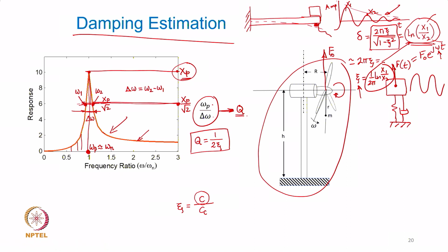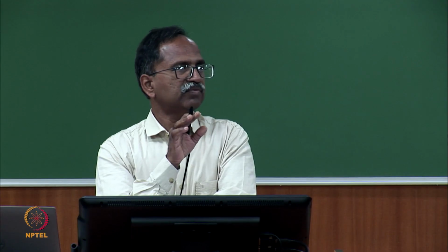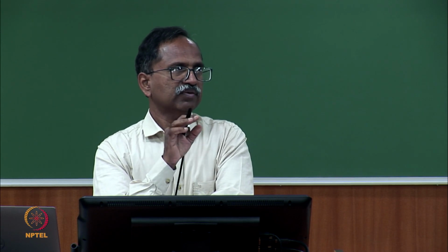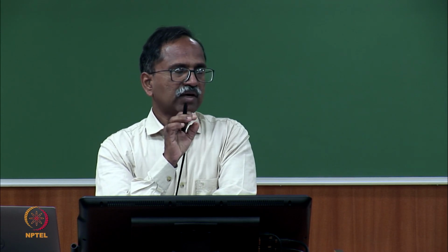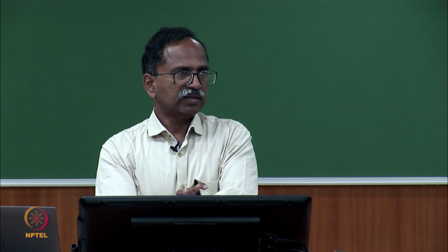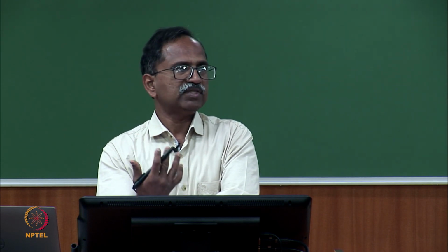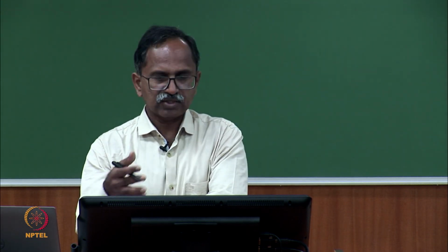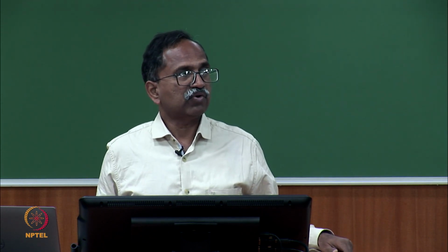This damping factor is an equivalent viscous damping factor, I mean the damping factor corresponding to the equivalent viscous damping coefficient C. So, it is C equivalent, because the system as such does not have any dashpot, there is no viscous damping here. So, we are saying that the damping which is equivalent to a viscous damping is obtained like this. That was the first damping estimate from a practical measurement process.